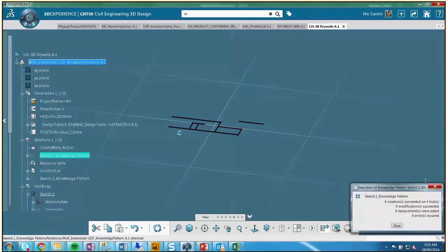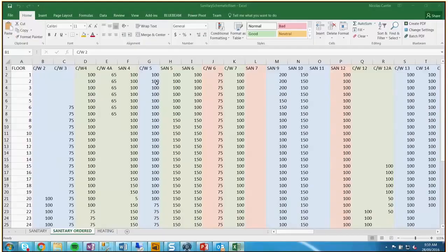And then based on the size of that, because we get plan layouts, and the plan view generally will have the size of the actual plumbing on it. So we can cross-verify by drawing the plan layout on the specific floor and sketching out all the locations of the stacks. We can cross-verify and cross-reference the size that we have from our plan view that we've drawn and copied with this schematic riser, because the schematic in mechanical is ultimately the driver of everything.